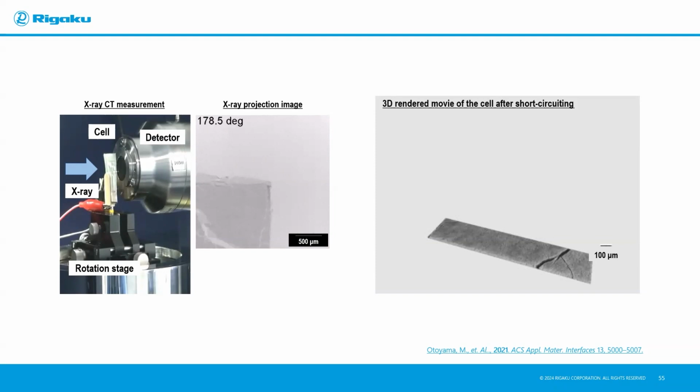Gotcha. It turns out that the accumulation of lithium and the creation of voids is a fundamental failure mechanism. Remember, I told you there's electrolyte inside, and the lithium ions require a continuous path of electrolyte in order to flow from the anode to the cathode and vice versa. If that's disrupted by some air pocket, then lithium cannot flow, and it essentially becomes trapped unless there's another mechanism or direction of flow.